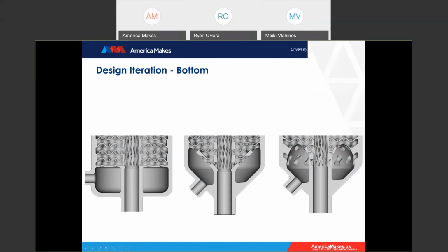Turning your attention to the far right-hand side is the final solution that we landed on. So we've added a 45-degree cut to the shell. We did a revolved elliptical cut out of the gyroid hex structure, which allowed both of those to then become supportless structures for printing.